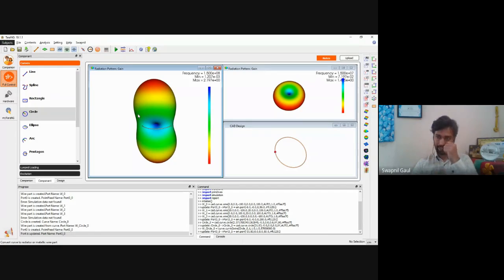The helical antenna is the antenna where we can get better directivity, and because of that we can use that antenna as a transmitter also, because earlier we saw that these loop antennas are not good transmitters because of the P rad and P in comparison we had. Here we cannot achieve more P rad, because of that we use these antennas as sensors. In biomedical applications, in sensor applications, we mostly see these loop antennas, but in transmission applications we don't use these loop antennas.